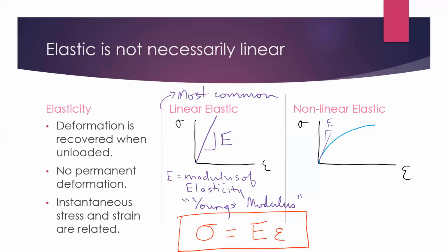And the elasticity, those apply for both, right? Linear and nonlinear. Yes. So for example, we could load this material and it would follow this curve up till this point. And then if we unloaded it, it would follow back down. And if you unloaded it all the way, it would go back down to 0. If you only unloaded it partially, it would end up at this point. But once you get to plastic behavior, that's not the case. And I think that's what next lecture is about, looking at plastic behavior.